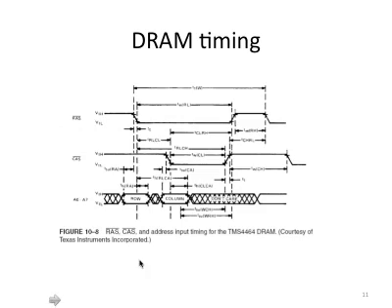In this timing diagram, we show the row address strobe and the column address strobe. Both of them are single-line signals, so you will see either high or low. The address lines A0 through A7 are a bundle, a bus, so sometimes it's invalid, sometimes it's valid.